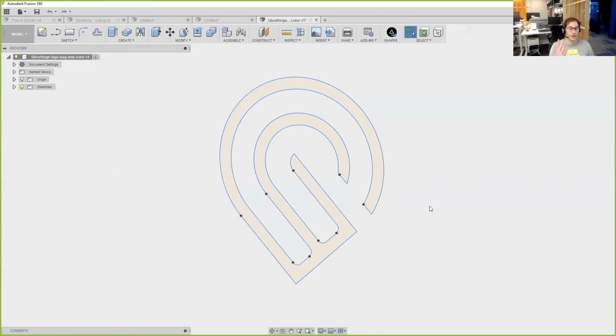So let's look at our 4 ways, and let's summarize what's a good choice, in my opinion, and what's not the best choice, in my opinion. Inserting the SVG came in no problem and allowed us to be able to rotate, scale, reposition, and everything. And it also came in with the actual entities. So for me, this one is my number 1 choice. I love this, right? That's excellent.